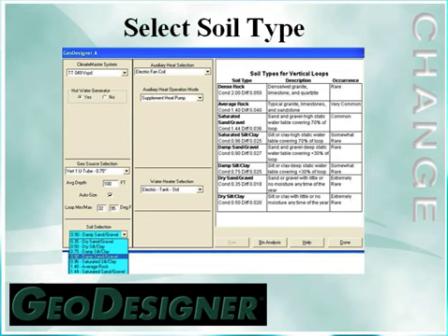That can be done with a simple hand test. Once we dig down into the ground, grab a handful of the soil, compact it in your hand. If a lot of water is gushing out around your fingers, you might have a saturated soil. If we're getting some moisture on our hands, a little bit of mud, it's a damp soil. If we were to take that ball of soil and set it down and it wants to fall back apart, we have a dry soil condition. That's just a quick method for you to determine moisture content. So again, we'll select the soil type for that location.